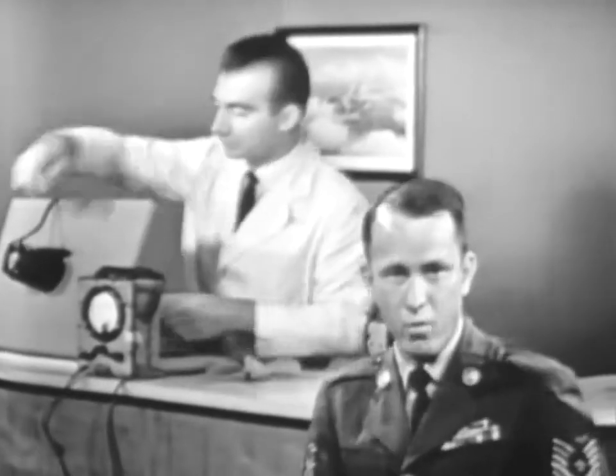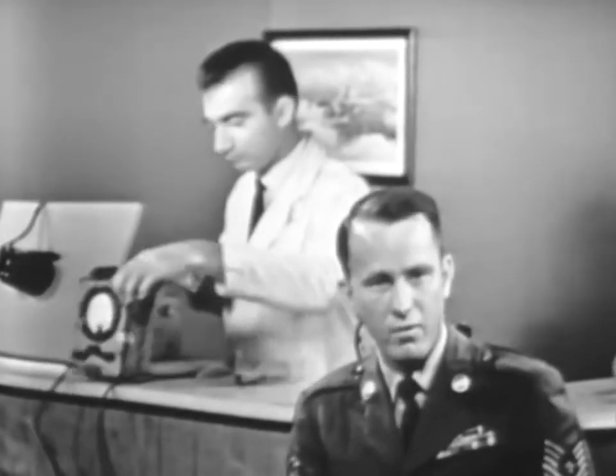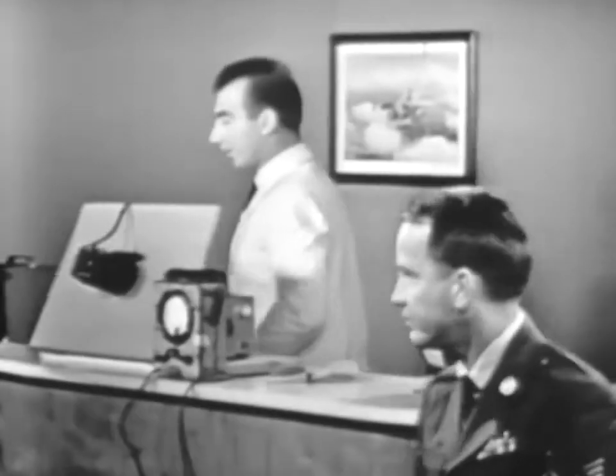Actually, there are two major points to discuss in order to understand how the induction motor operates. First, we must have a rotating magnetic field produced by the stator windings. And second, we must cause the rotor to become an electromagnet. So let's first determine how we can produce a rotating magnetic field. Okay, coming up.